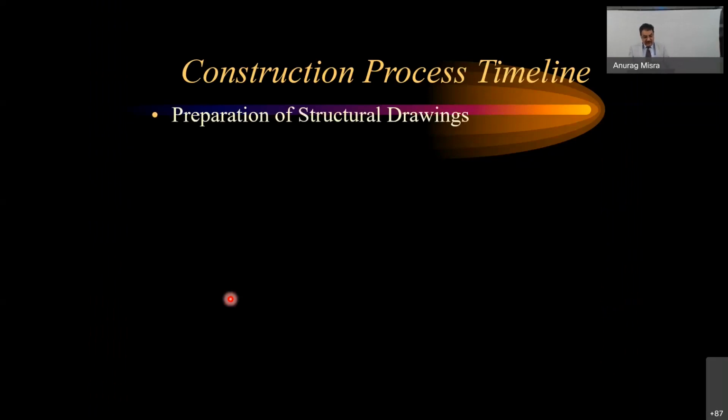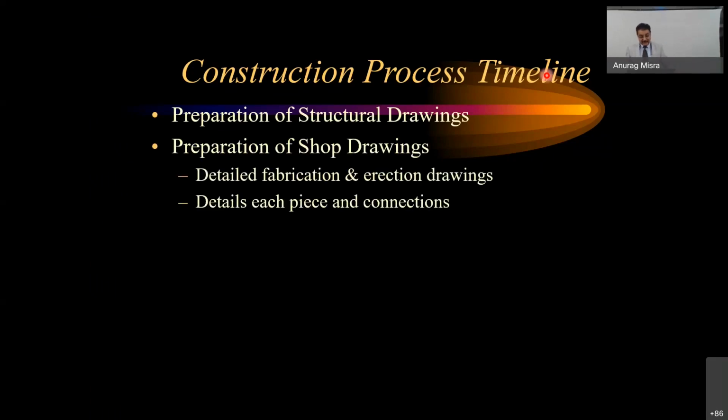So how are we going for the construction process timeline? Preparation of the structural drawing. And when I say structural drawing here, those GFC drawings are not good enough, because you have to draw the shop drawings. Detailed fabrication drawing, each component is drawn so that every hole has to match wherever it is meeting the other one. So each piece has to be